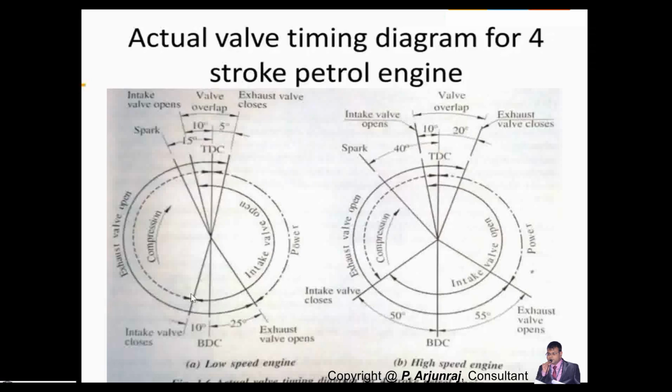So neither the exhaust valve will open nor the inlet valve open. So here you're giving a chance for the compression to take place without any loss, without any pressure drop. The compression is going to happen such a way that it moves from BDC to TDC, compressing the air and the fuel in the case of gasoline, whereas in the case of diesel, only the air gets compressed.